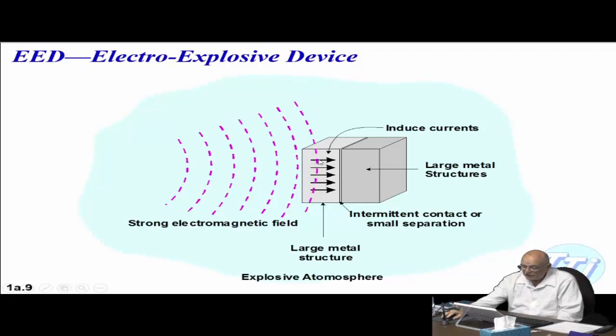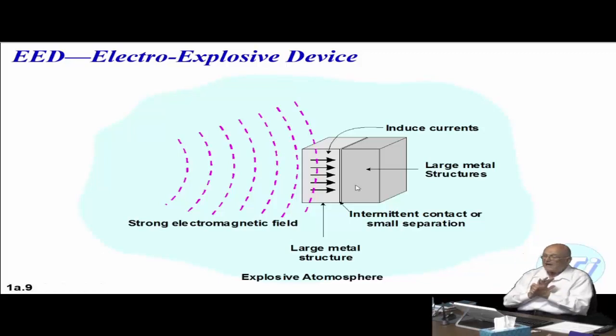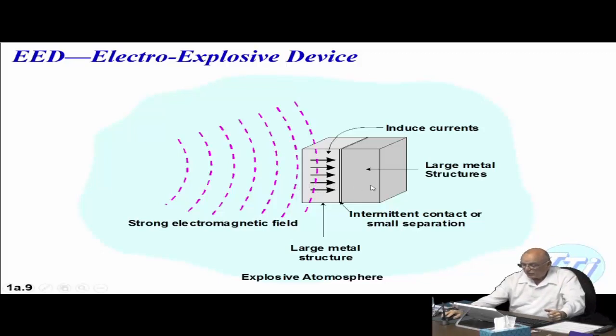And that internal current, if these 2 pieces of metal actually are just touching off and on, intermittent, it'll cause a spark or an arc directly. If they're welded together and they're solid, it'll just create a current, which will not actually create the spark, but it's these 2 pieces of metal together that are not joined really tightly.